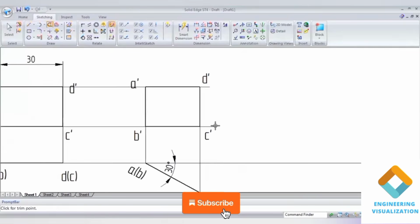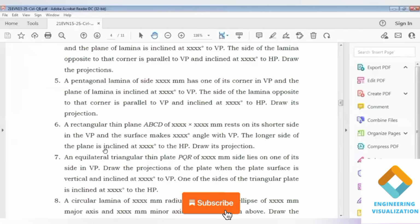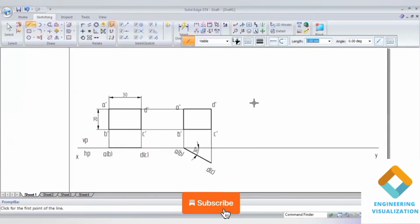And trim off these extra lines. You can see now the longer side of the plane is inclined at a certain angle to VP. That means we should take that longer edge and we have to give the angle of inclination here. First I'll be drawing an angle line. Angle of inclination here I'll give 45 degrees.